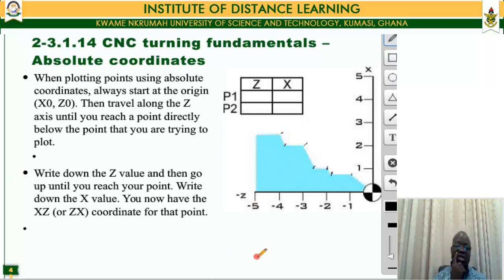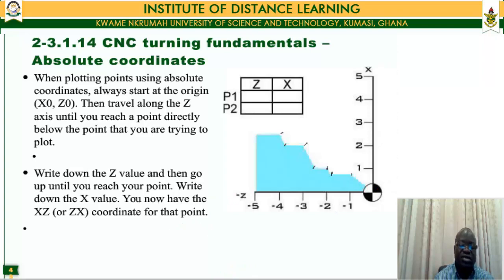So you notice that we can actually create 7 coordinates, and we are starting them as an absolute coordinate system. So we start off at 0 here, and because we are programming on the lathe, the tool starts at 0, 0, with the work position at negative z. So any movement on the z axis is seen as a negative movement into the workpiece. So that is basically some fundamentals here.